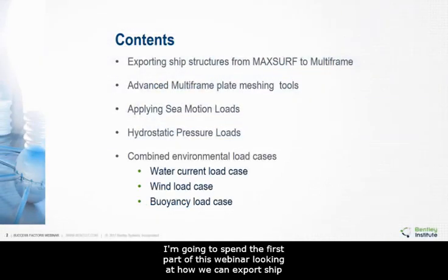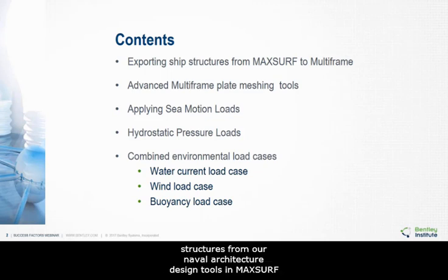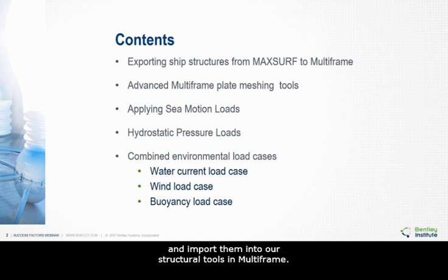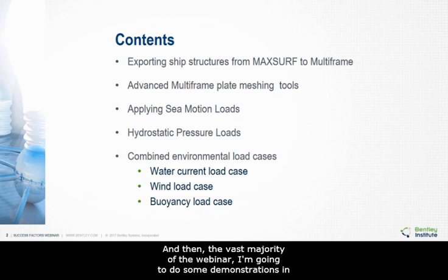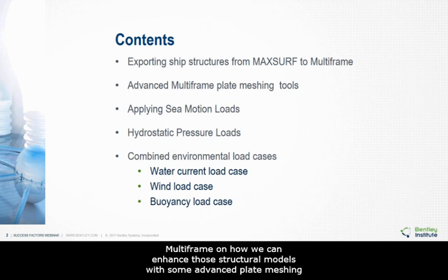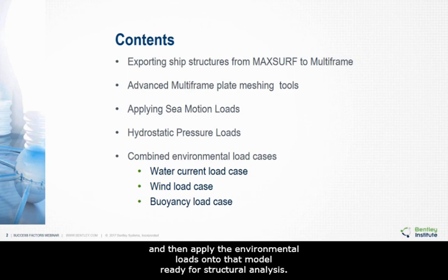I'm going to spend the first part of this webinar looking at how we can export ship structures from our naval architecture design tools in MAXSURF and import them into our structural tools in MultiFrame. And then the vast majority of the webinar I'm going to do some demonstrations in MultiFrame on how we can enhance those structural models with some advanced plate meshing tools, some of which are particularly specific to the marine environment, and then apply the environmental loads onto that model ready for structural analysis.